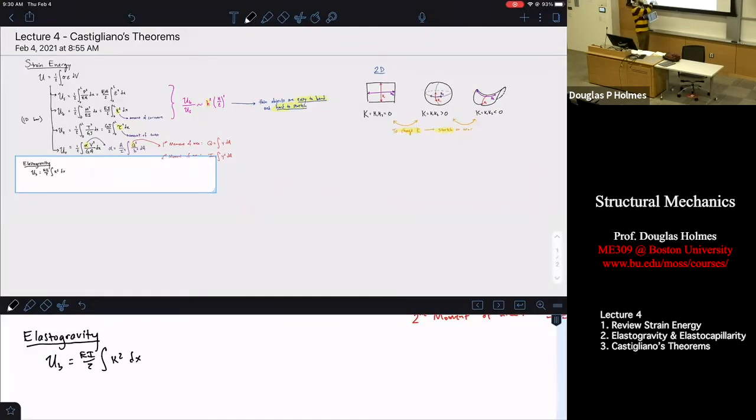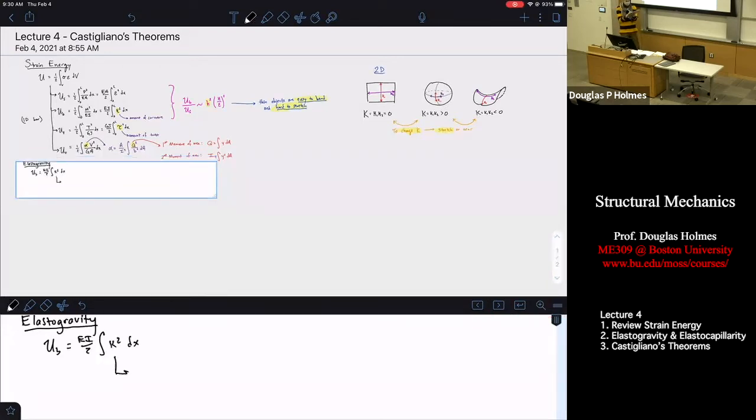So we can make a small angle approximation in here and say curvature, we know, has some complicated definition related to, well, I'll just show you what it is. You might not remember. Curvature does this. It's like the second derivative of deflection over 1 plus your first derivative of your deflection, which is your slope, squared. Oh, I might not have enough room. Let's see if I can do this.